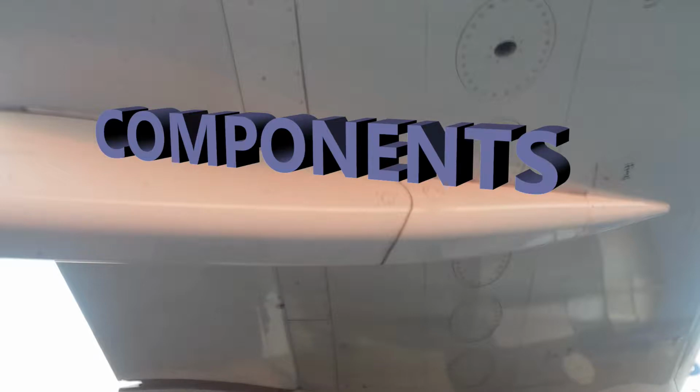So basically, if one of those sensors becomes dry, because these are in the tank, then the control unit is going to send a signal to the FADEC to close it, and then stop the recirculation system essentially. You also have 2 temperature sensors as well. So it just gives you an idea of the different sensors that you have going on with this entire fuel system.